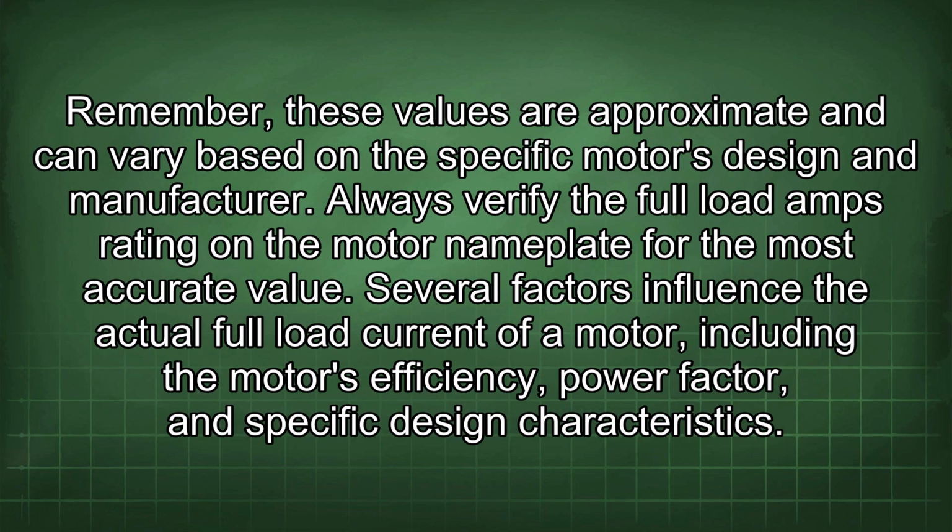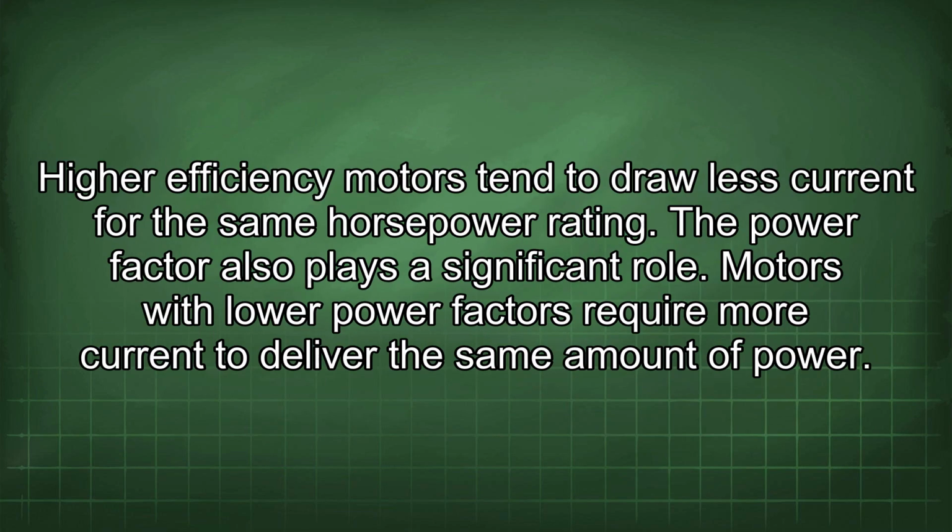Remember, these values are approximate and can vary based on the specific motor's design and manufacturer. Always verify the full load amps rating on the motor nameplate for the most accurate value. Several factors influence the actual full load current of a motor, including the motor's efficiency, power factor, and specific design characteristics. Higher efficiency motors tend to draw less current for the same horsepower rating.